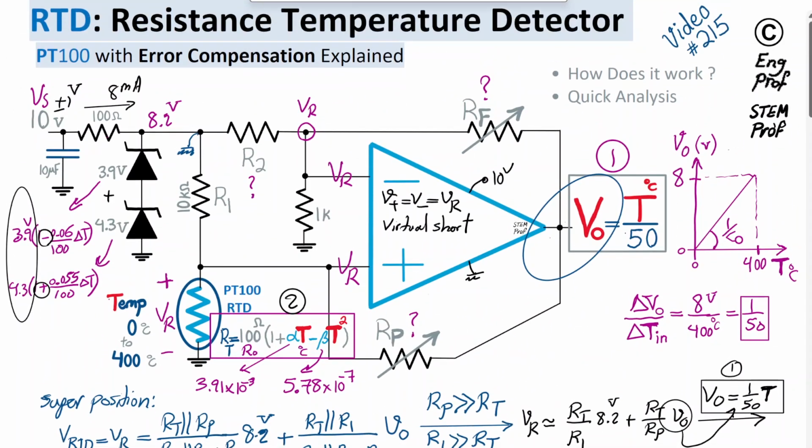I'm going to write a KCL at this node, basically starting from VR. So there are a bunch of currents that are going out. So I have this current, which I refer to as I1. I have this current that I refer to as I2. And I have this current that I'm referring to as I3. This current here is 0, of course, practically speaking, because the input current to the input terminal of the op-amp is 0 because its input impedance is practically infinite.